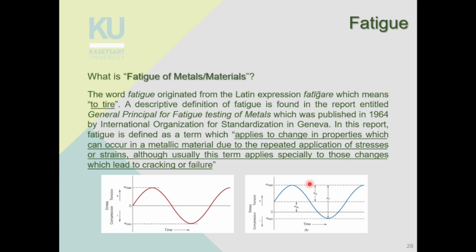You apply stress in cycles, and that will cause cracks or fracture, even though the maximum stress, sigma max here, is less than the yield strength of the material. So you shouldn't even get plastic deformation. If you're applying a constant stress, you will not get plastic deformation, but because you're applying a cyclic stress, you can break the specimen.